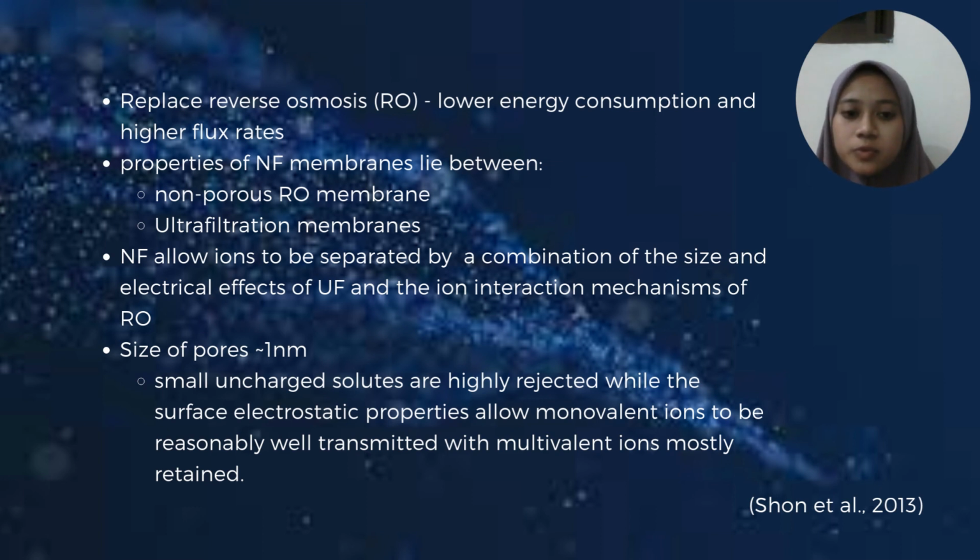The properties of nanofiltration membranes lie between the non-porous RO membrane and the ultrafiltration membranes. NF allows ions to be separated by a combination of the size and electrical effects of ultrafiltration and the ion interaction mechanisms of reverse osmosis.